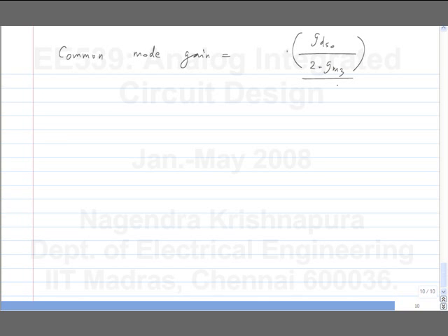The obvious way of reducing the common mode gain is reducing the value of GDS0. Okay. How would you do that? So again, first you can try to increase the length if you are interested in only the DC quantity. Then if you increase length and width by a large amount, that will increase the parasitics. So you can go to a cascode current source.